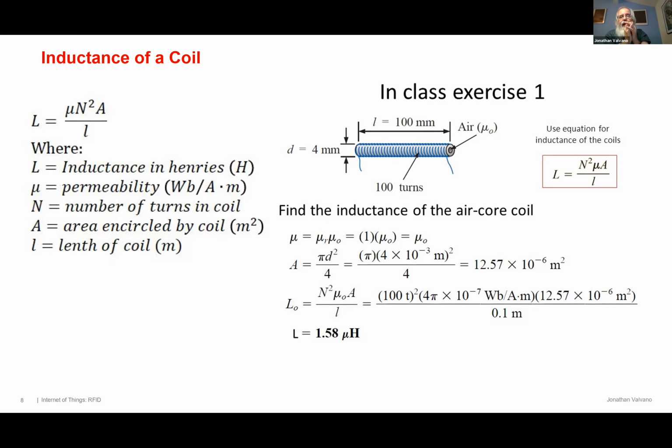Interestingly enough, you don't stack them like an electromagnet. I don't know if you've ever taken an electromagnet apart, but you can coil it on top of itself and try to make L large. That doesn't work. But A is the area. The problem with A is the A2, the one in the embedded device. You want that to be very small so you can embed this little module into as small a space as we can.